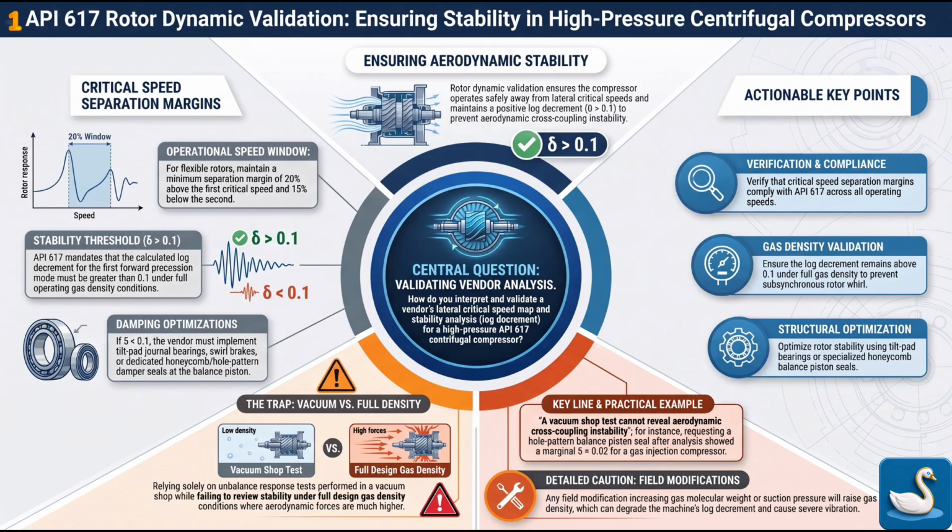So taking that next logical step, you demand the stability analysis at full field gas density, and the calculation comes back with a log decrement below 0.1. The machine is mathematically unstable.